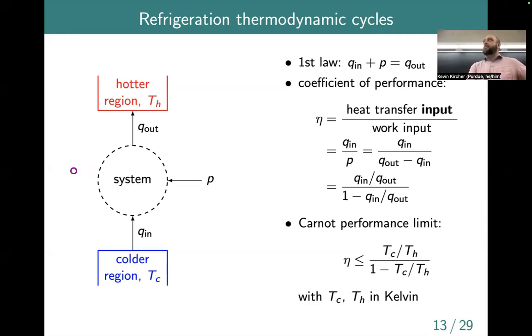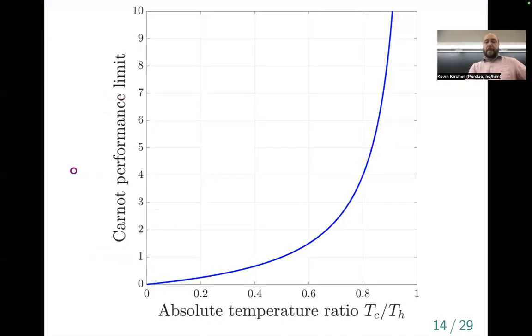Although I think that most of the waste heat, if the machine is designed well, should actually go into the refrigerant ideally, and then it would go to the condenser and be bled to the outdoor air. But yeah, I don't think many air conditioners have a compressor inside, and I think it's not primarily for that issue so much as it's a rotating machine, it gets noisy, so you'd rather have it outdoors. Yeah, but it's a good question. And then we also get the same kind of blow up behavior here in the COP curve. So when the temperatures become approximately equal, we get potentially nearly infinite COP.